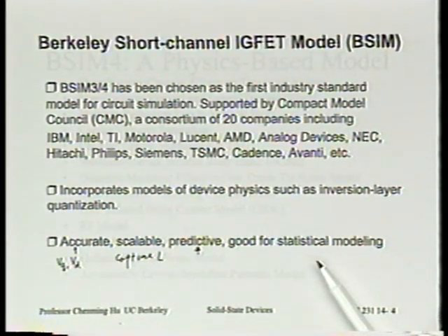In a SPICE model, if we just measure the statistical variation of oxide thickness and plug that into BSIM, because BSIM immediately translates that into its impact on the various aspects of the transistor, that certainly will make this a good model for statistical modeling. You see the point, right? How can you use curve fitting to do that? How many statistical devices are going to fit? And how do you use them mathematically?